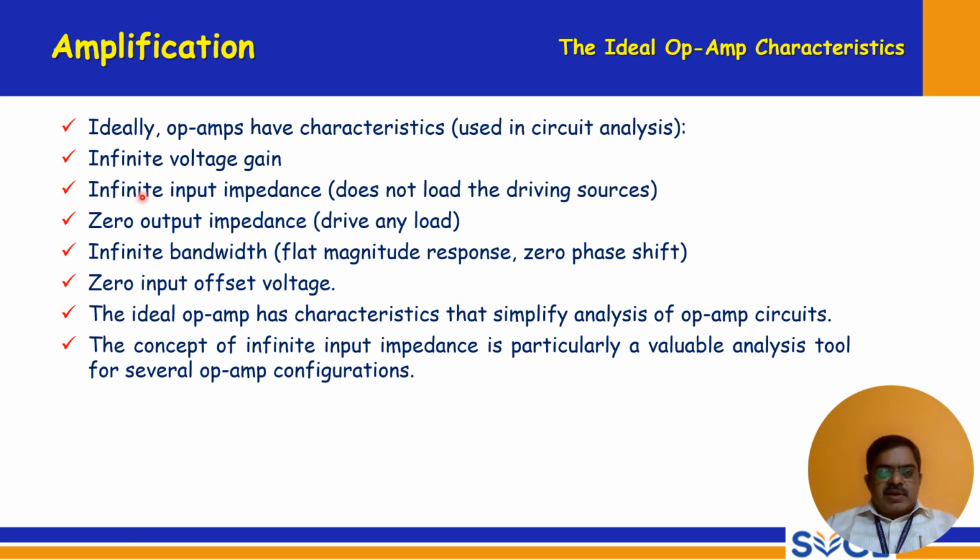Here are the ideal op-amp characteristics, as I said in the earlier slide. Ideally, op-amps have the following characteristics used in circuit analysis: infinite voltage gain, infinite input impedance so it does not load the driving sources, zero output impedance so it can drive any load, infinite bandwidth, flat magnitude response, zero phase shift, and zero input offset voltage.